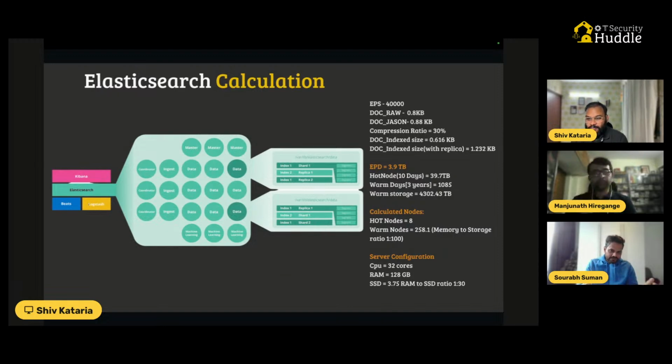And then if you have all those things, apart from that, do you have intrusion detection systems? Do you have continuous monitoring systems like Dragos, Nozomi, Clarity? If you are at a good maturity level, let's suppose maturity level 3 or 4, or 3 and above, then definitely go for all those defense in depth principles, whatever has been taught in NIST guidelines or in 62443.